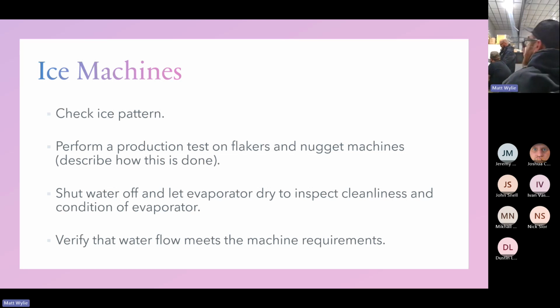So S's would be, if I recall, S is usually 404, so an SC is going to be medium temp, and an SZ is going to be low temp. And then I think the V's are the 22 valves. So V's would be for anything like 22 or a replacement 22, which I think your chart says like 448, 449, 407, anything that replaces R22. 507 and 404 only.